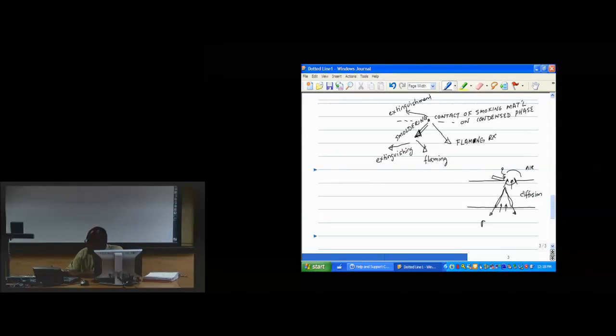So all of a sudden we've switched from a scenario in which the external heating element is causing the pyrolysis to occur to one in which the flame that we've set up as a result of the initial ignition of these degradation products becomes self-sustaining and begins to liberate more and more pyrolysis gases that will then continue to burn and sustain itself.